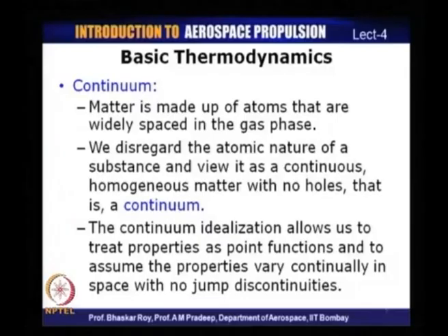So, the other principle or assumption that we are going to make is known as continuum. Continuum refers to the continuity within a system. I will explain that shortly. Now, as we are all aware, matter is made up of atoms which are widely spaced, especially when it comes to the gaseous phase. In classical thermodynamics, we would want to disregard the atomic nature of a substance and view it as a continuous homogeneous matter with no holes or void, that is, it is a continuum.